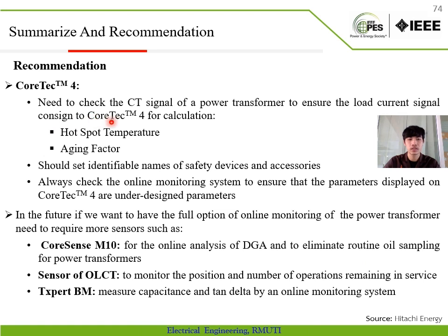Recommendation: need to check the CT signal of the power transformer to ensure the load current signal goes to Cortex TM4 for calculation of hotspot temperature and aging factor. Should set identifiable names of safety devices and accessories such as the self-dehydrating breather of the on-load tap changer and main tank, and oil level of the on-load tap changer and main tank. Even though we have an online monitoring system, we need to check it to ensure that the parameters displayed on Cortex TM4 are under our design parameters or not.